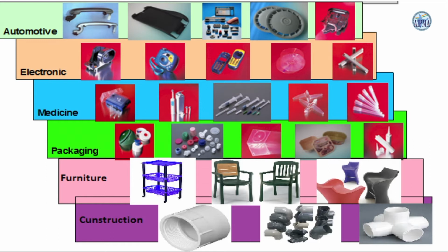This process involves melting of plastic raw materials by heating and plasticizing in barrel and screw, and then the melt formed is injected under pressure into closed mold and cooled. Cooling melt takes the shape of the mold cavity and you will get molded part.